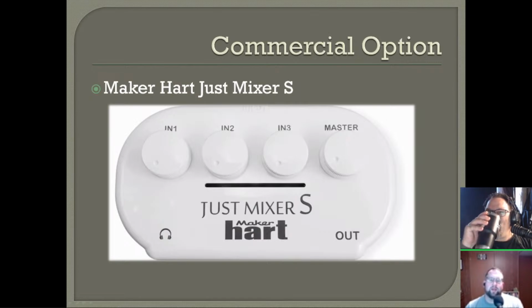From there, I investigated some home-built solutions and followed a walkthrough on building a line-level audio mixer from Bob Heil. I believe that was on Ham Nation episode 164, if anybody's interested. This handled mono audio and was pretty easily adaptable to a stereo solution by changing the potentiometers there. I also found a video on, I believe it's Matt Sub YouTube channel, that covered building a 5-channel passive audio mixer with stereo pots.